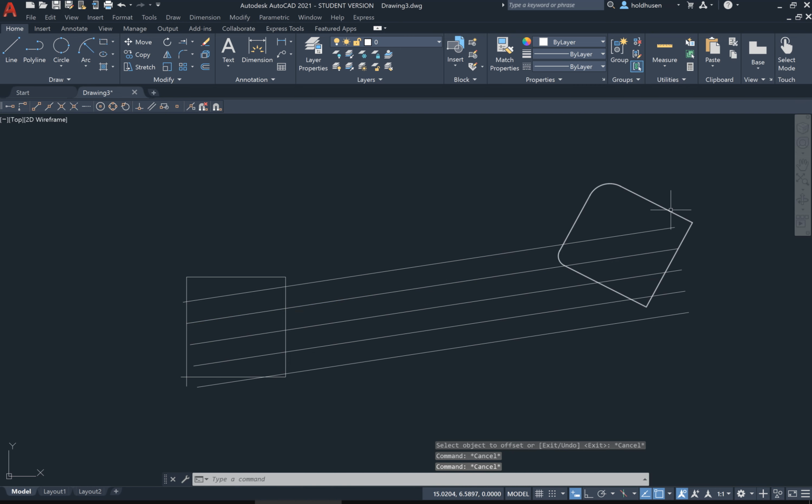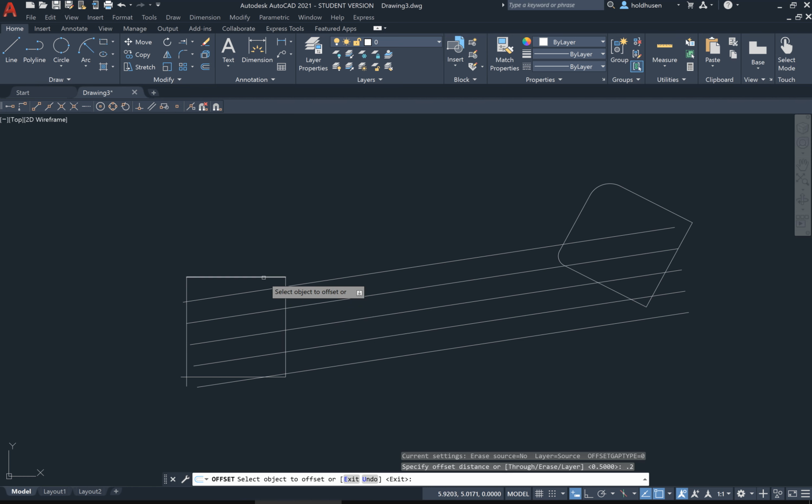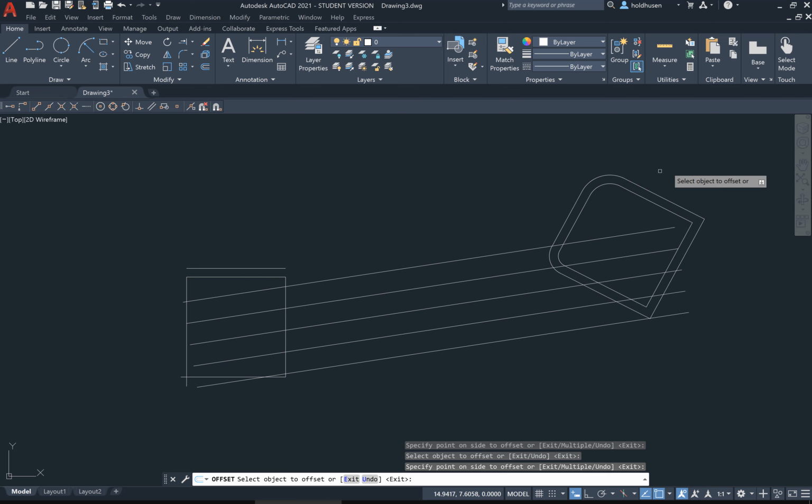It's nice doing this offset command with this polyline, which is one of the advantageous things of doing a polyline. Let me do the offset again. This time I'll just do 0.2 for my offset, right? If I try to do an offset for this square, I can do it, but I have to do each line individually. Whereas if I come over to this, and now it's a polyline, I can click that offset, and it'll take the whole line and offset it the 0.2. Or I can go inside, of course, as well, if I need to. Okay, so that's one advantage of creating a polyline, doing that offset.